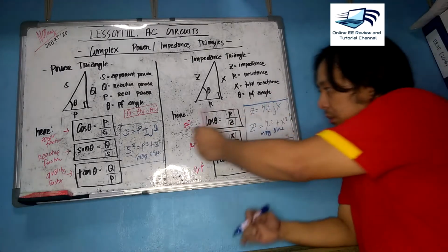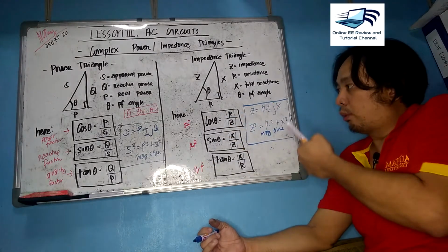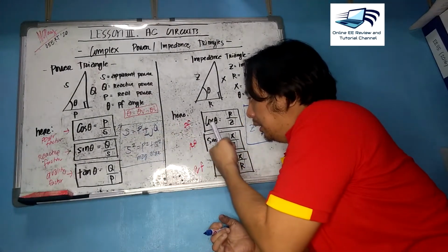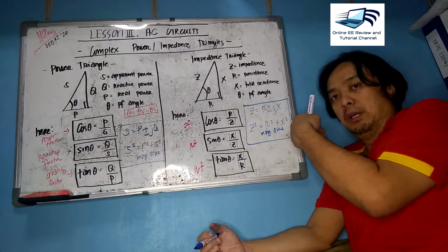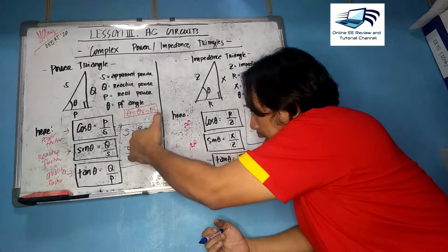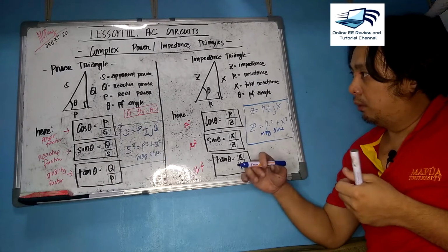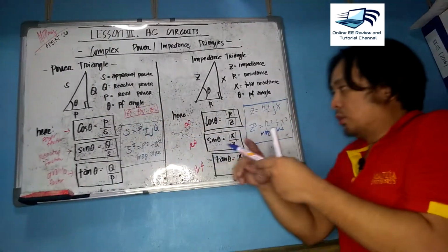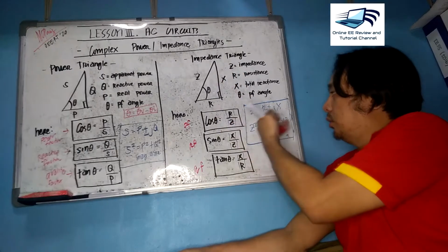And why is it plus or minus here? It is simply because it can be a reactive or reactance component, which means capacitive or inductive. So it can be inductive or capacitive power, and it depends on why it is plus or minus. The line here is in the positive side, so you can have positive, and if the line is purely capacitive, which is on the downward side, you can have negative.